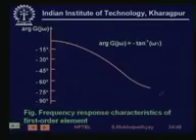Similarly, if you have a phase plot, then as you go to higher and higher frequencies, the phase lag increases, and the maximum phase lag possible for a first order system is 90 degrees. So it will gradually approach 90 degrees.